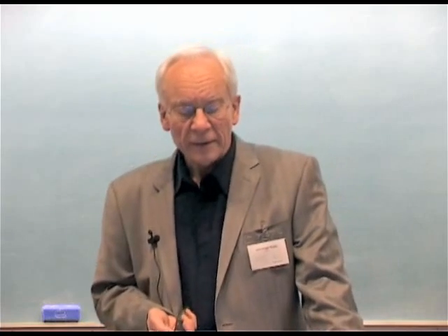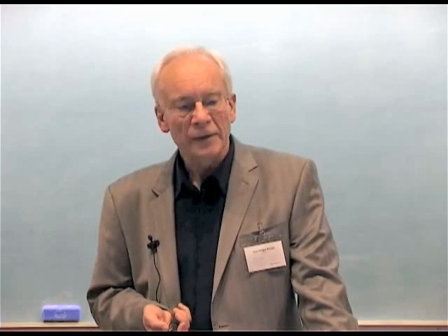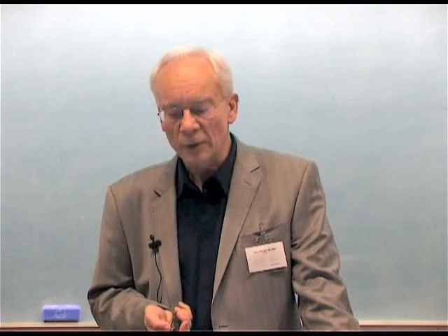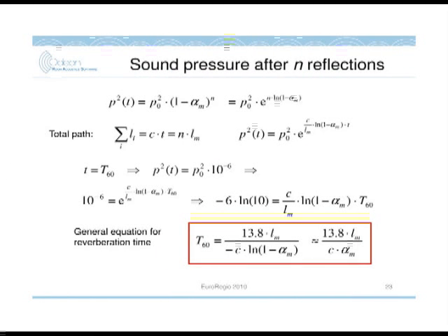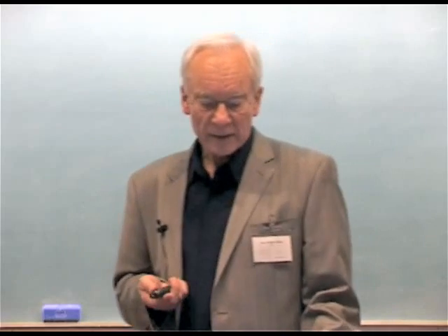After each reflection, the sound energy will be reduced by a factor of 1 minus the absorption coefficient. For the beginning here, we can assume the same absorption on all surfaces. If you do that, it is possible to set up equations to calculate the sound energy after a number of reflections, n. That corresponds to a time, and after a time equal to the reverberation time, there will be a decay of the energy to one millionth of the initial energy.